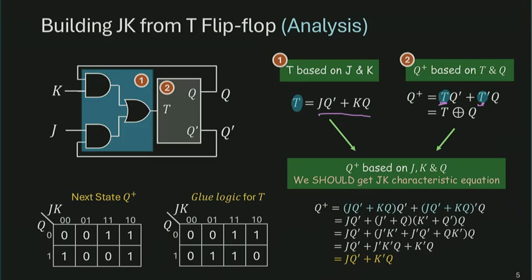So, trying to evaluate the sequential circuit, and evaluation happens at two stages. I have to go through the combinational logic and then the internal characteristic behavior to find out the q plus. I'm just trying to combine those two evaluation stages into a single expression so that I can directly describe q plus in terms of the primary inputs and the current state.